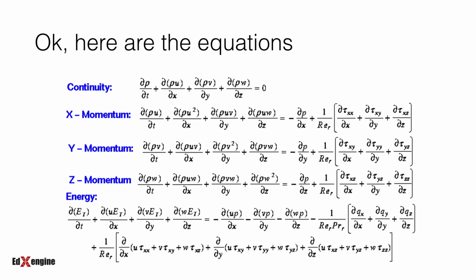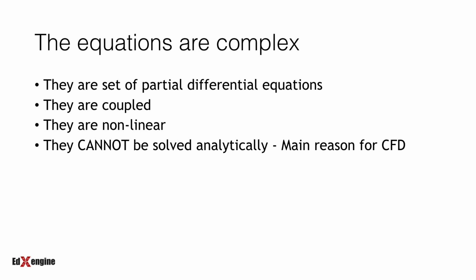And finally, when you take a look at the energy equations, you see that you have similar terms. You have a time derivative term and several spatial derivative terms. At this point, we are not going to talk about these terms, and when we derive the governing equations, we will be paying attention to them. So the main takeaway about these equations is that they are coupled and they are nonlinear, and that they cannot be solved analytically. The fact that it cannot be solved analytically is the primary reason for the existence of CFD.